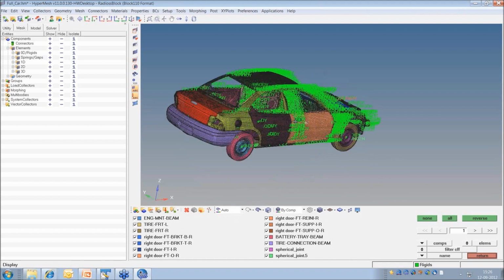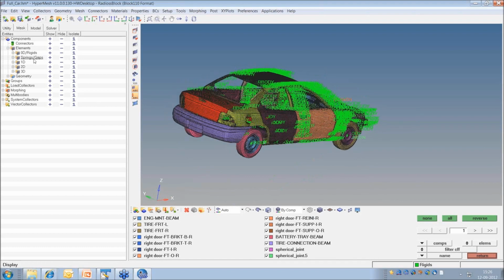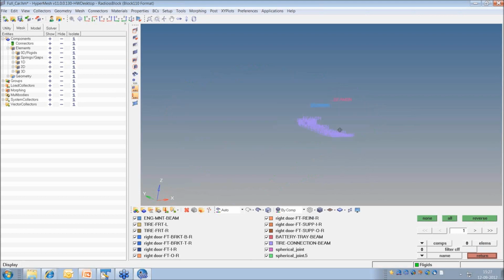The next activity is for the beams. I have some beams that are the structural beams at many locations for different applications. I'm not going into detail. This is, I think, for the hood attachment, maybe, but I'm not going into detail. I will just create a beam property and update the same property for all these components.